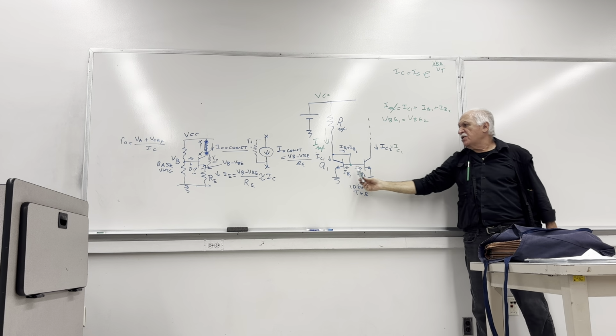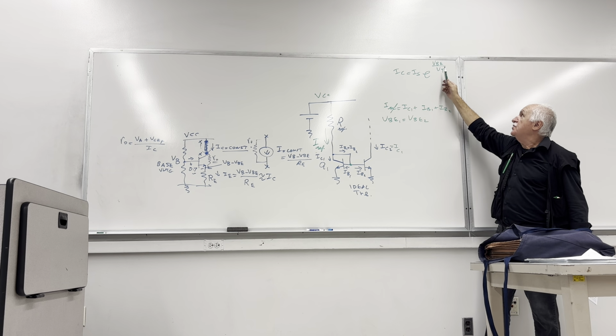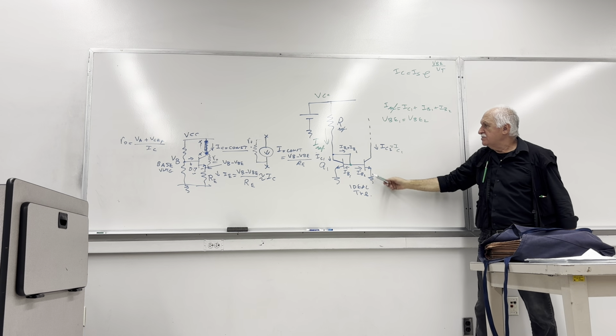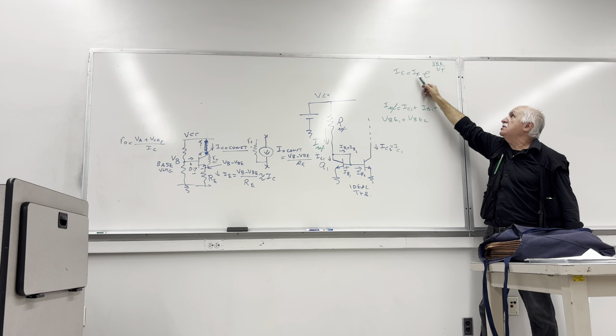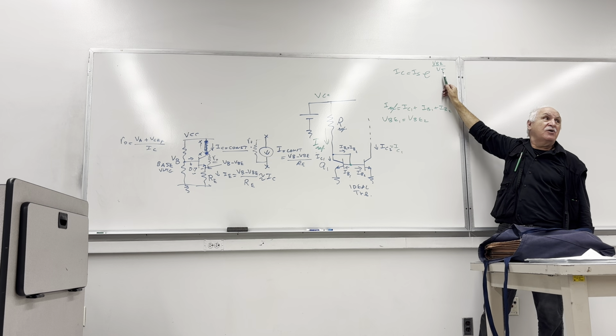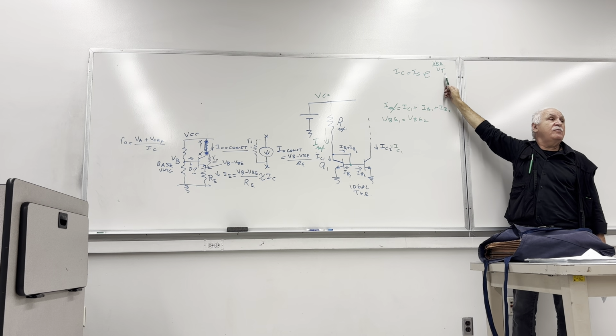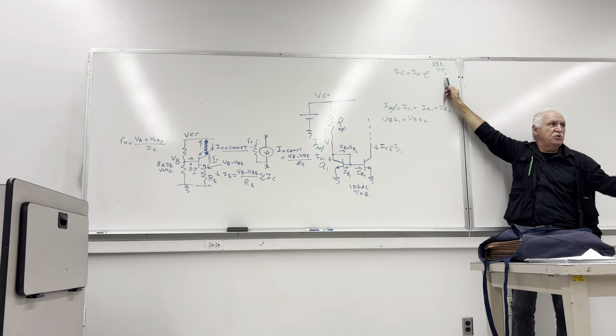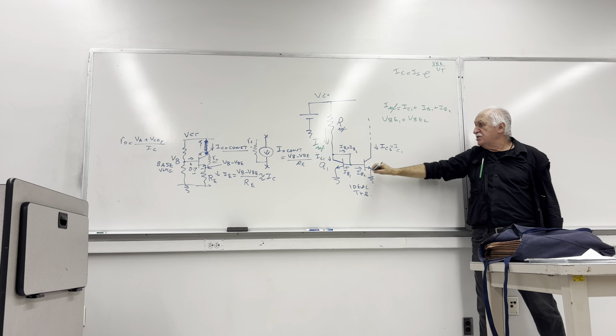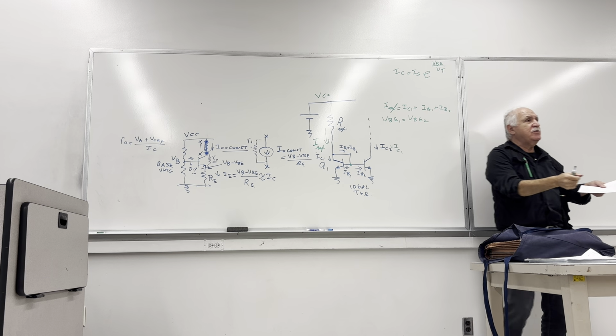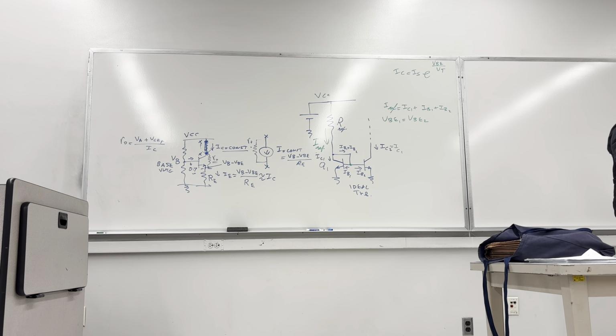If the two transistors are identical, their VBEs are identical, and their ISs are identical, and their temperatures are identical, VT. VT, remember, is room temperature dependent, kT over q. But if these two transistors are fabricated on a chip, an IC, which is like 10 micrometer by 10 micrometer in dimension, they're practically right next to each other, thermally. So they will copy each other's temperature, identical temperature. Therefore, VT will be identical.